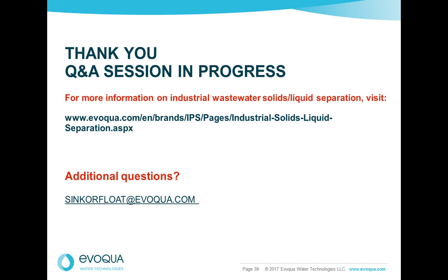We do not directly, but others within Evoqua do. And you're seeing more applications where people are trying to put UF membranes downstream. There is a challenge, especially in applications where the BODs are still quite high, which can lead to increased fouling of the UF, and also any coagulant or polymer that's used prior to flotation can carry over and create fouling issues with the UF membrane.